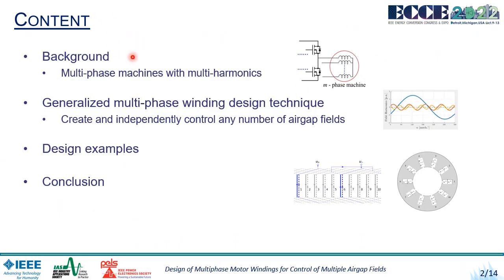In this presentation, I will first present the background for multiphase machines with multiple harmonics, and then present a generalized multiphase winding design technique that we have developed, which allows creating and independently controlling any number of air gap fields. We then present design examples to demonstrate the use of this technique in designing multiphase windings.